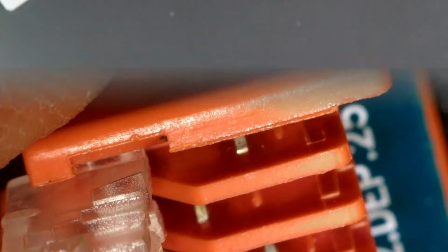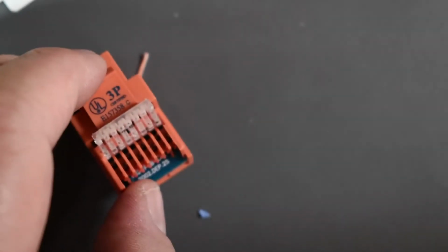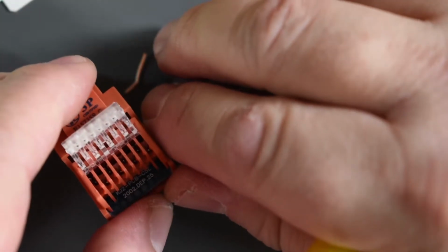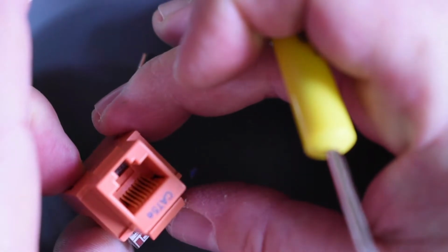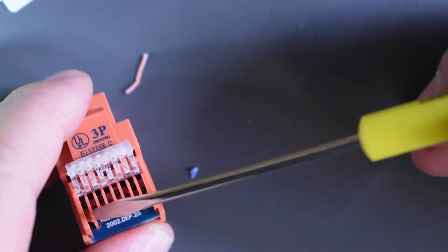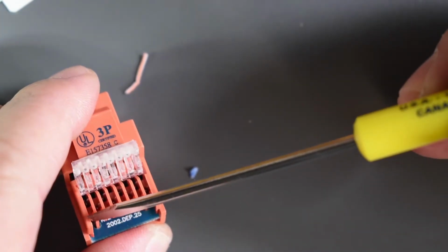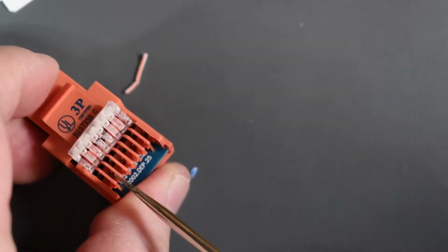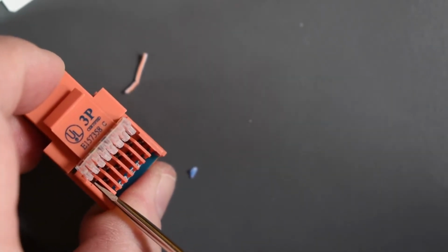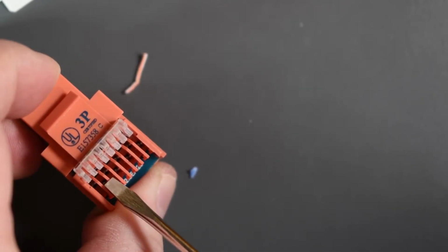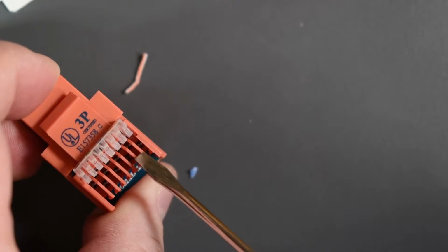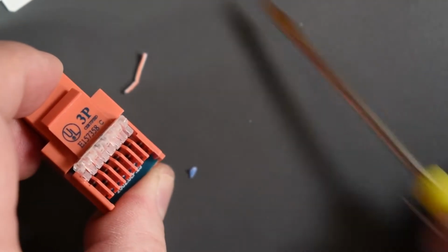Now, if you look at it a little bit like this, you can tell that some of the IDC connectors are closer to the front of this jack. So that's the front of the jack. And some of the connectors are closer to the rear of this jack. I'm not sure if you can see it here: here's one that goes this far, and there's one that only goes this far. So they are kind of interweaved, all right? You have to make sure that you insert the wire past that. And this is how you do it.